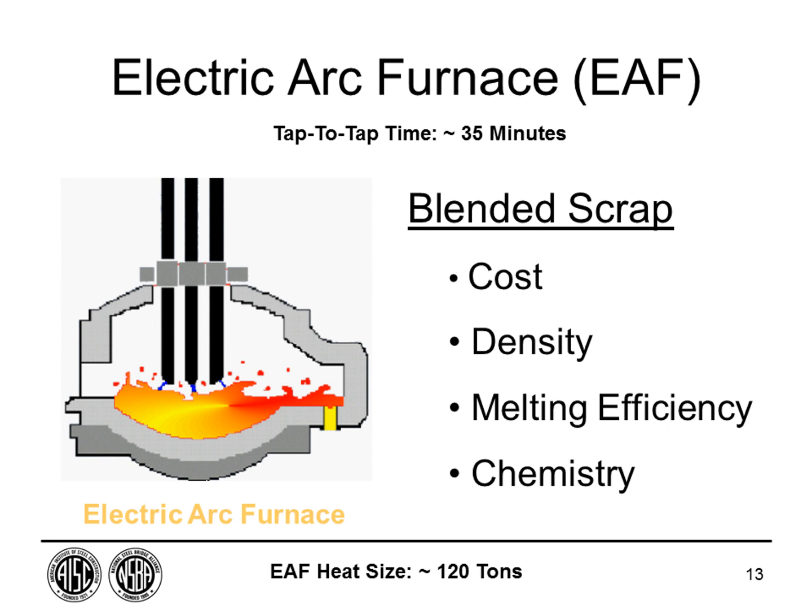And it's done in an electric arc furnace. And these are smaller furnaces than the conventional integrated mills. But basically, they can melt a heat of steel in 35 minutes. And it uses electrodes, carbon arc electrodes, which are used to melt the steel. The scrap is actually segregated, and they have different qualities of scrap. And that determines really the chemistry of the steel. It's a very efficient process. They can very quickly melt the steel.